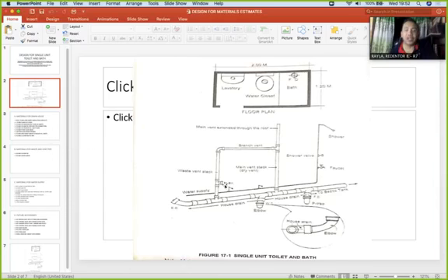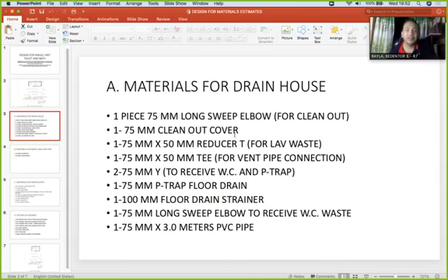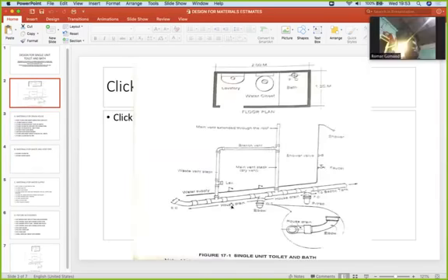The bend for the lavatory is 75 by 50. So that's the one. 3-inch pipe. Reducer. It's a reducer pala. So it's not the T. Here is the reducer. This one, it's hard to see, they look the same. 75 to 50 reducer. 3 to 2 inch. Copy.